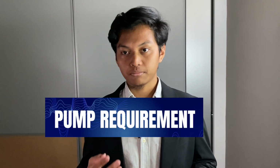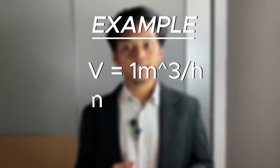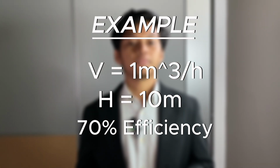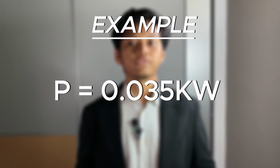Let's touch on the pump requirements. For this system, the friction factor, determined by the flow conditions and pipe characteristics, affects the power we need. For example, for a flow rate of 1 cubic meter per hour, a 10 meter head, and a 70% pump efficiency, the required pump power is about 0.035 kilowatts.